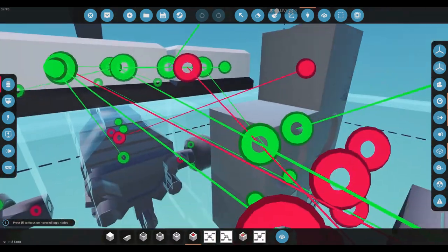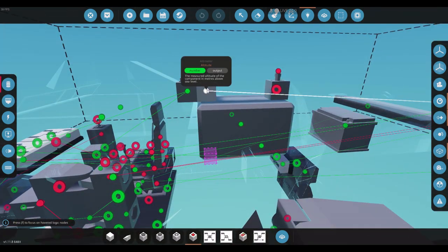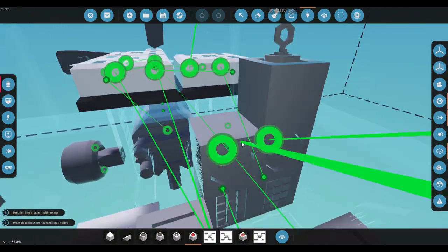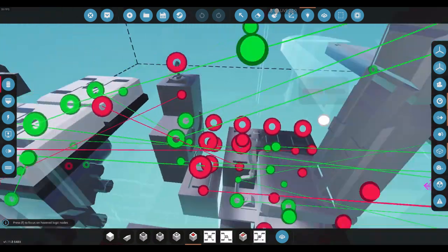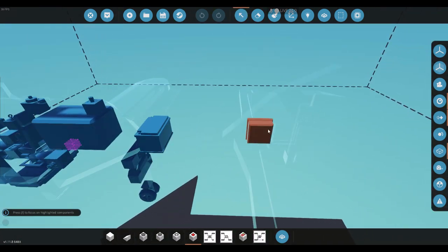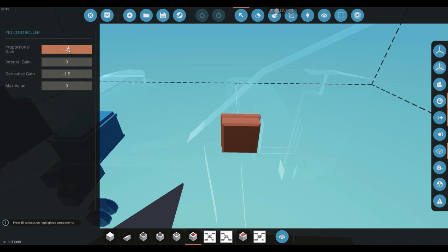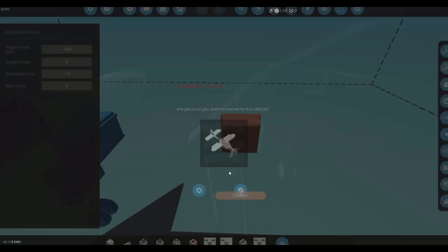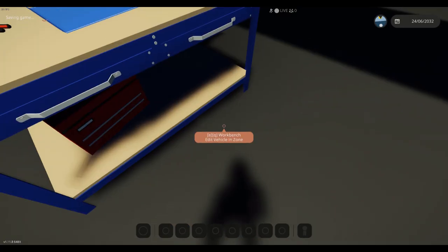This is probably something more realistic in terms of this guide. Aha, so look, we hooked the altimeter up to the PID process variable, but we forgot to hook it up to our dial. That's going to be very important, because we're going to want to be reading our current altitude. And for the PID, I noticed the plane was skyrocketing a little bit. So we're going to add another 0 here, but I'm worried that it would be too weak if we did that. So I'm going to make that a 2 or maybe a 3, and then we'll see what this system does. So, advanced tutorial, or advanced plane. Yeah, this is what we're working with.